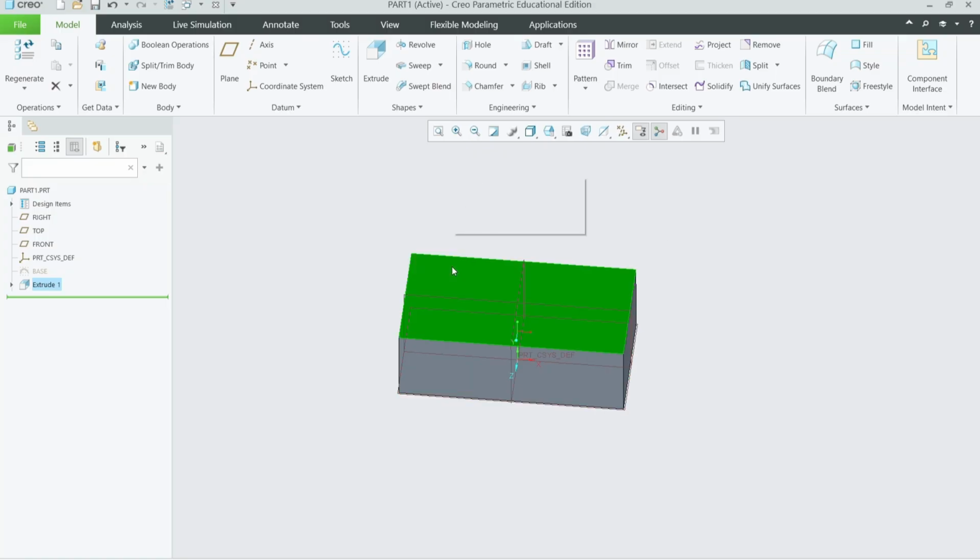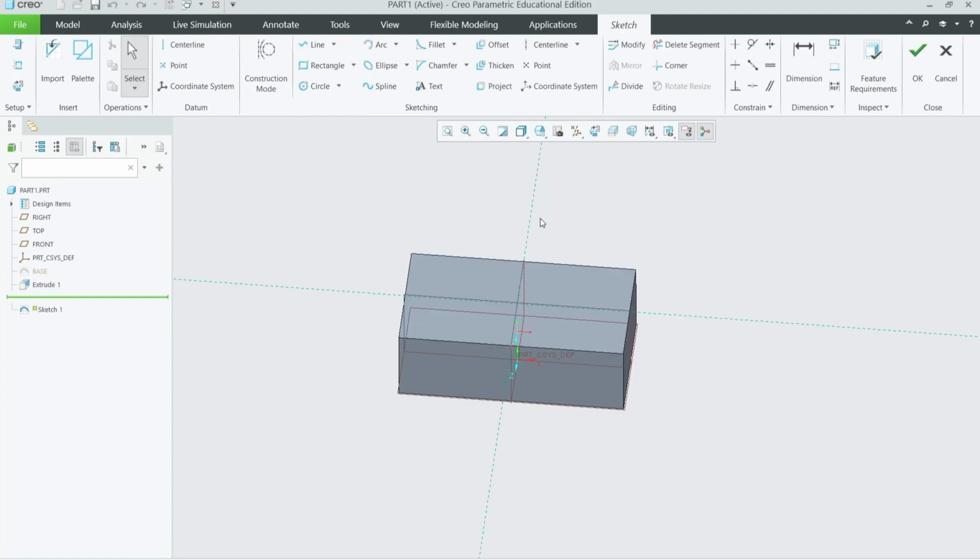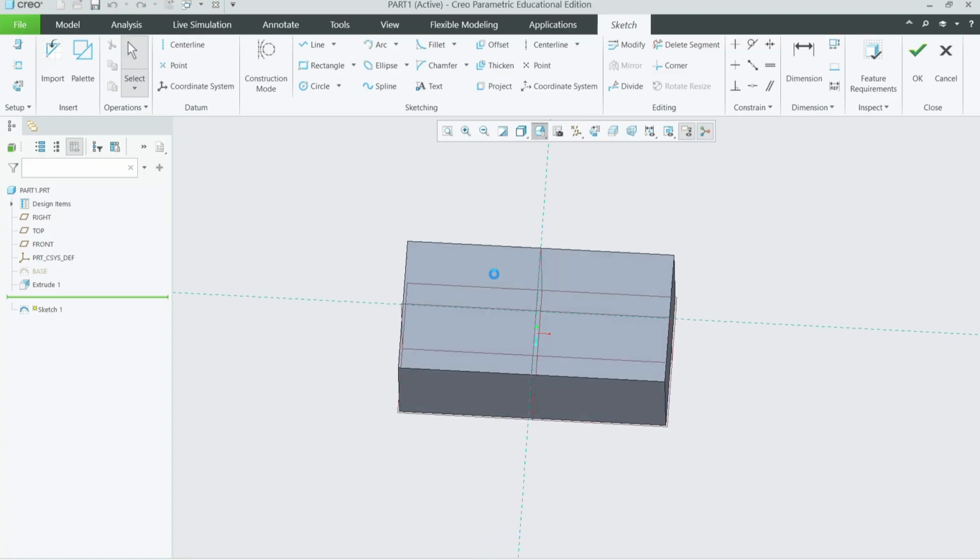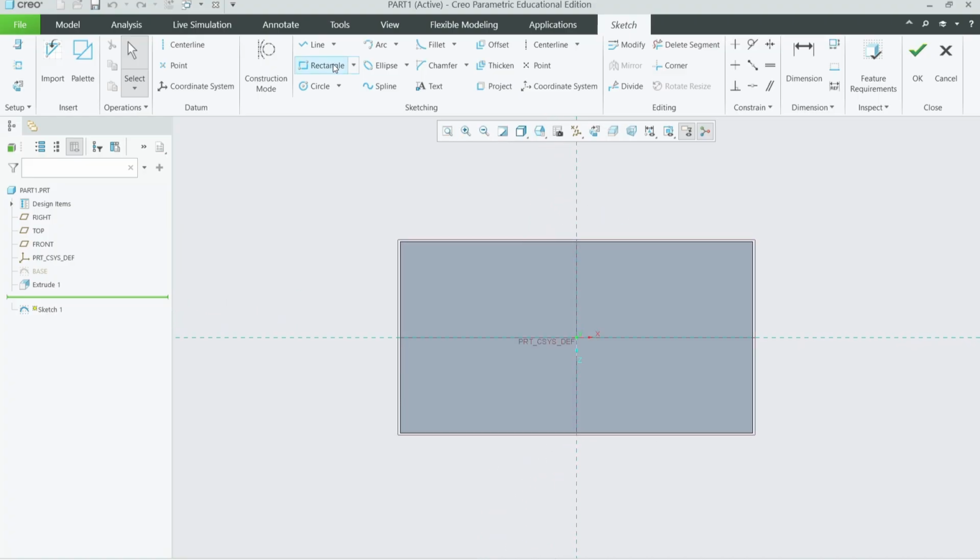So the process is going to be very similar to what we just did with a rectangle, but this time the rectangle creation is going to be much simpler because the points are going to simply snap onto the already created rectangular points that we can see in this top view head on. So create a rectangle on the far left side of your rectangular base, 3D geometry, top view, and then type in your dimension. In this case, it's going to be 25 inches. And then hit enter. Make sure you have a center line because we're going to mirror this.